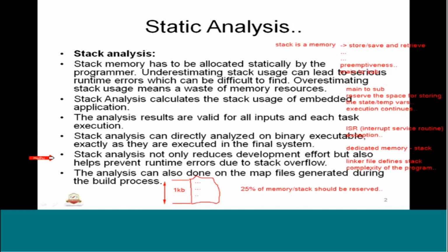Why? Because the programmer knows about the program he has developed, but there are different things along with it, such as libraries he could have used, where he is not aware of how much stack they are going to use, and certain assembly code he doesn't know how much it is going to occupy the stack, and certain support functions or subroutines, or third party hooks or code which he is not aware of.